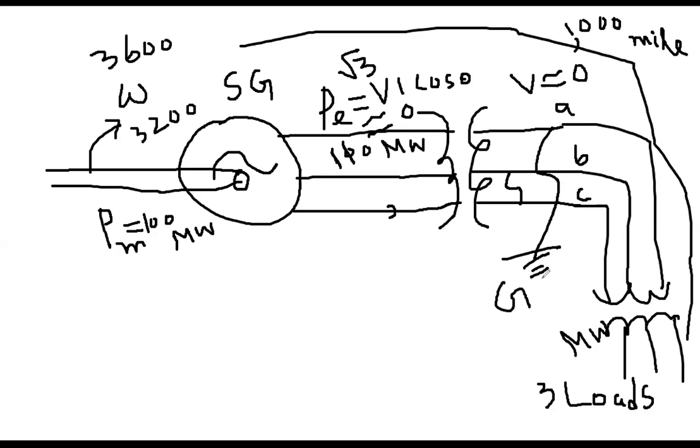Its root is on the ground, but portions of the tree or branches got stuck on the three phases, and that caused a short circuit. Because the tree is a good conductor. Whatever the leaves or branches, they are good conductors. There is juice or sap inside those. So they may cause a short circuit, and short circuit plus grounding.